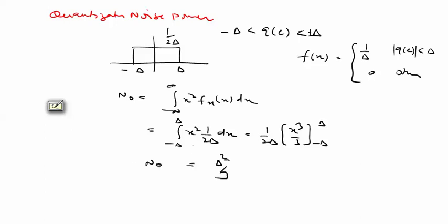Now the noise power will increase. We are now using an optimum condition, meaning a minimum number of levels and a minimum number of bits, at the cost of sampling. So the noise power is raised by 4 times compared to the previous case, but the total noise power is spread uniformly over the bandwidth fs. The power within bandwidth b is b upon fs.